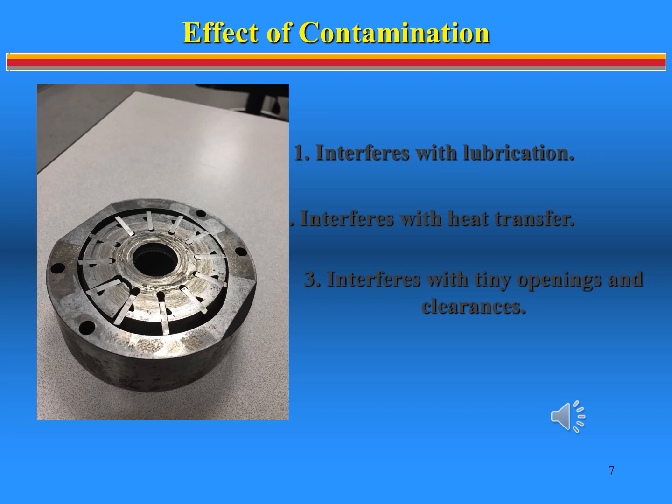Dirt causes surface scoring, produced when abrasive particles flow across contact surfaces of hydraulic seals. Clearance honing, from dirt flowing through spaces between moving parts, creating greater clearances and destroying critical tolerances. Fluid degradation. Fine metallic particles act as a catalyst promoting the chemical breakdown of your fluid.